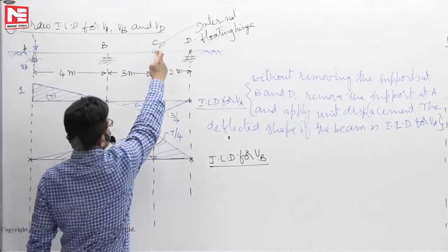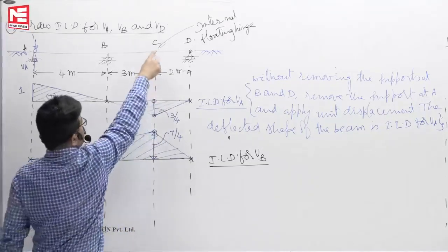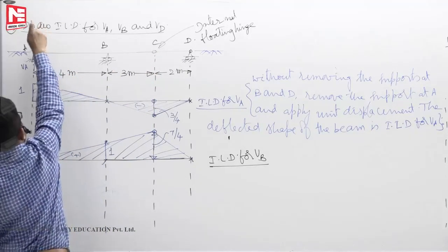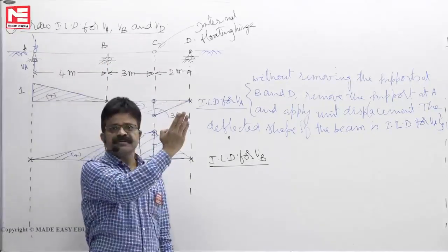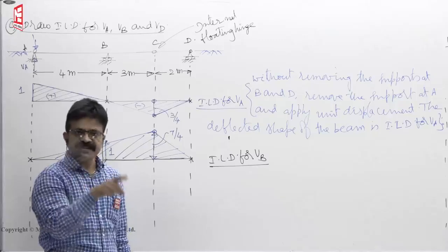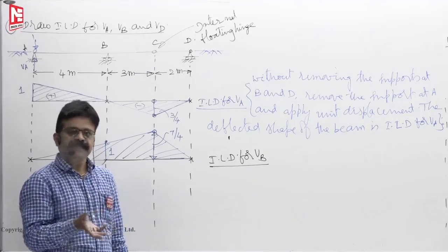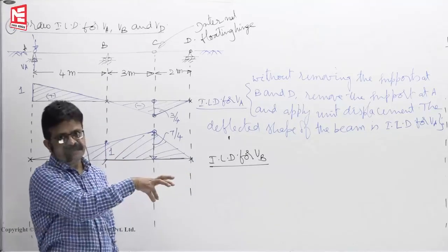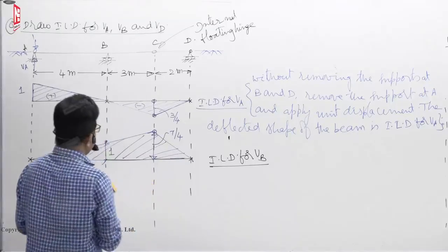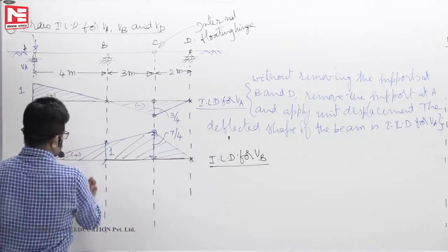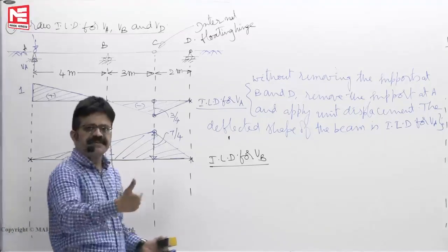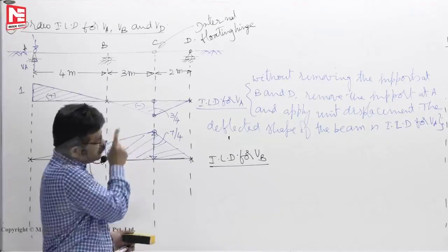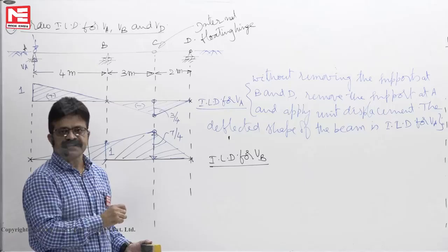See, here you see, when you apply load here, it is supposed to go down. If it is going down, this should go up. If you don't permit this to go up, I have to pull it down. Then here the reaction is more. That additional force in steel structures, we call it prying action. So those prying actions, when we take up steel structures, I'll again explain with these examples how we have to make it, and how many ways the T sections, etc., will fail. We see the prying member design, whether they are safe or not, also we have to discuss. That means the observation of this we apply in the design of steel structures also.